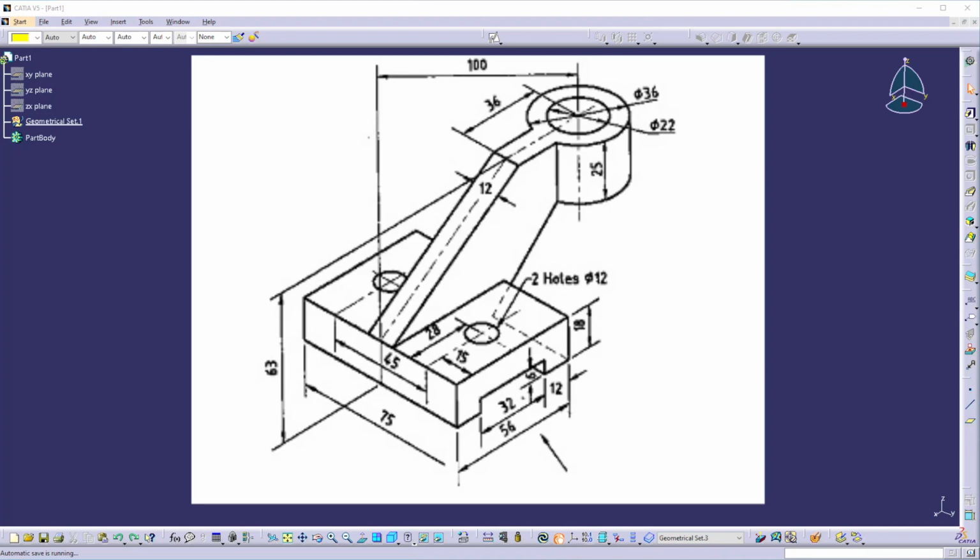We're gonna build our initial model by considering future possible changes to the part during its development, because the component may change from time to time due to changes in the surrounding part, changes in the mating part interface, or due to some reinforcement suggestions after CAE analysis. To do these modifications quickly and easily at any stage of the design, we have to build our model properly with the proper combination and sequence of operations. And we also need to keep a proper parent-child relationship between the elements and the features.